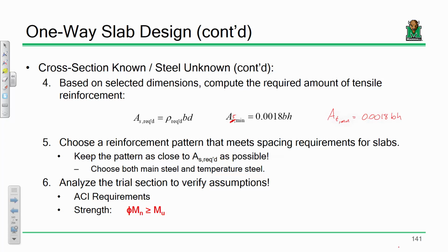Remember we talked, for those of you that aren't in steel design, we talked, was it last week, about what happened on 64, the expansion joint and all that? Well, related to that, buildings expand and contract. Slabs expand and contract under thermal load, under shrinkage and temperature changes. Well, slabs, by their very nature, are inherently thin. Because of that, they're much more susceptible to cracking under thermal changes and under shrinkage and so forth. So we add another layer of steel acting in the other direction.